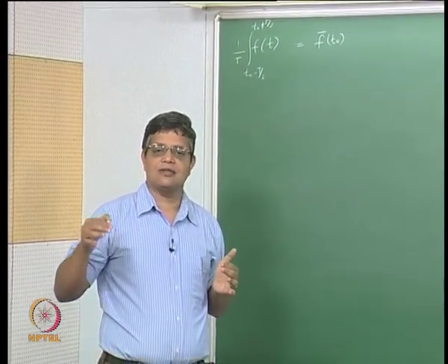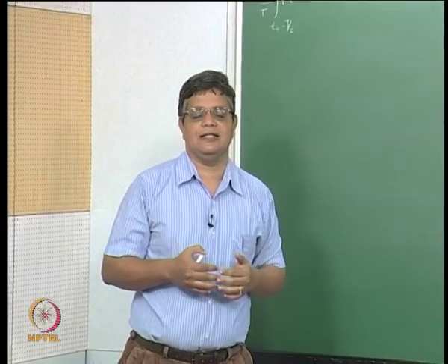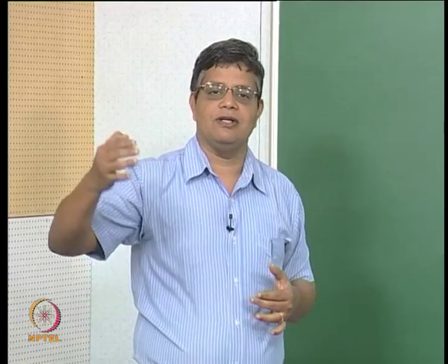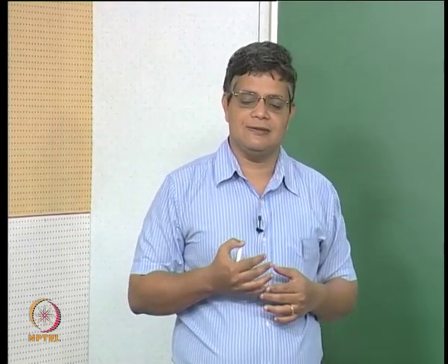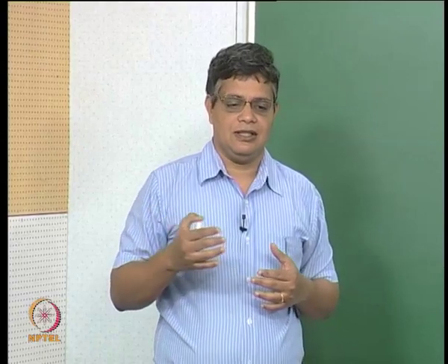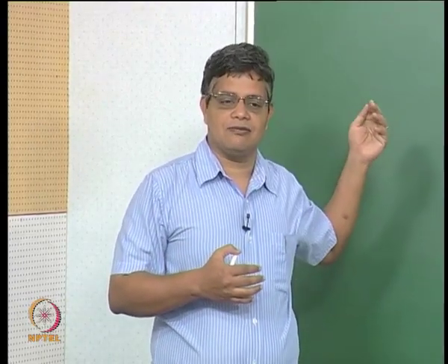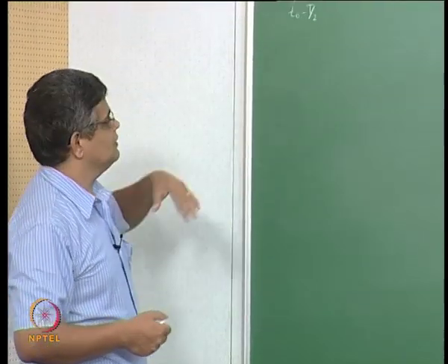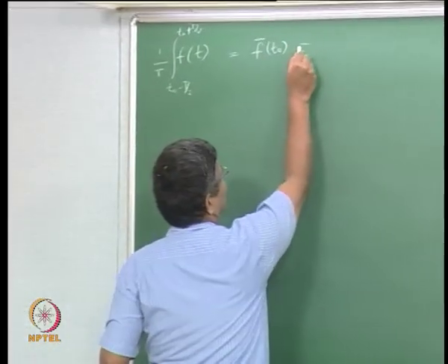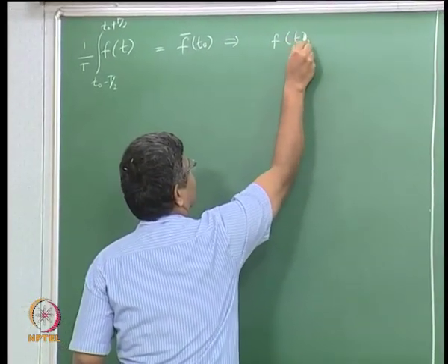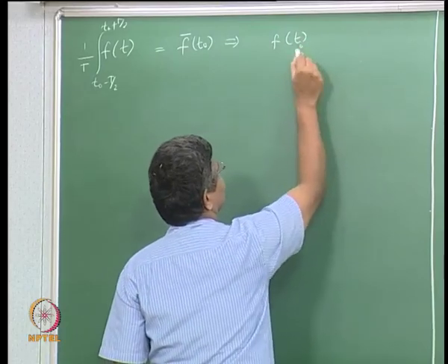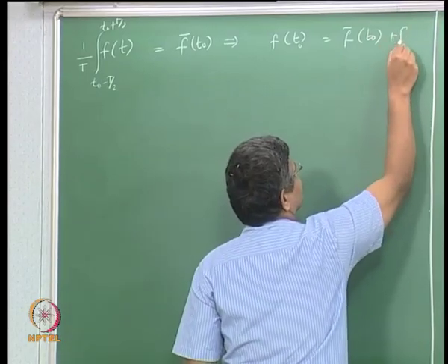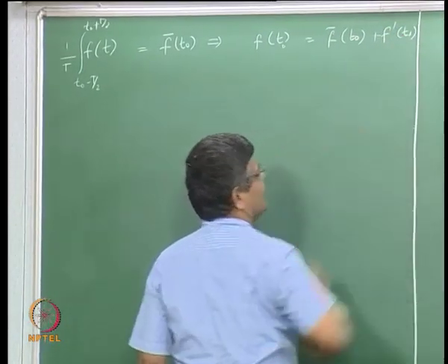The system transients that we are usually interested in, for example the startup of a particular chemical reactor over a period of minutes or hours, are very long compared to the typical time period of fluctuations produced in turbulent flow. So this enables us to do this decomposition: we can write f at a particular time t0 as f bar at t0 plus f prime at t0.